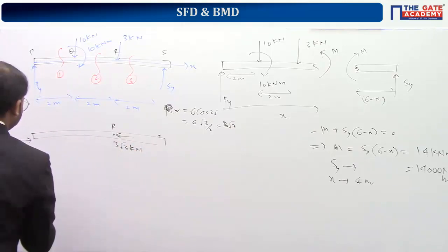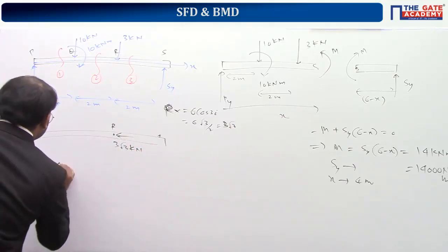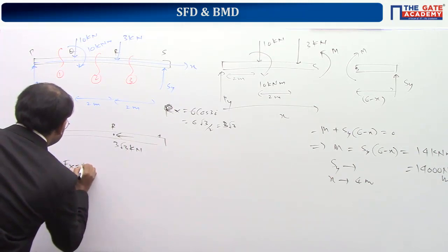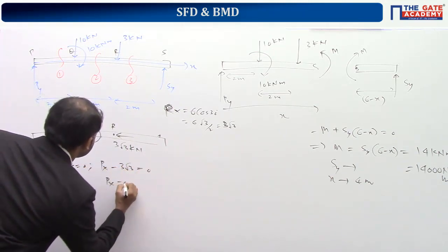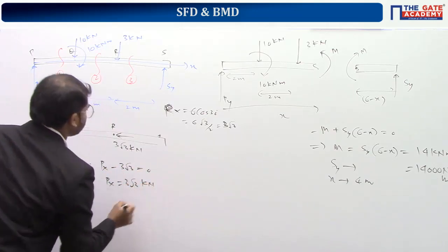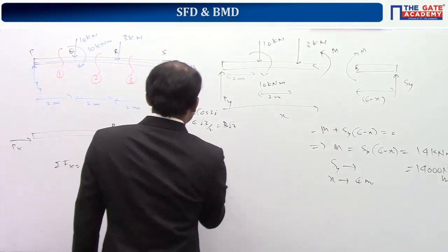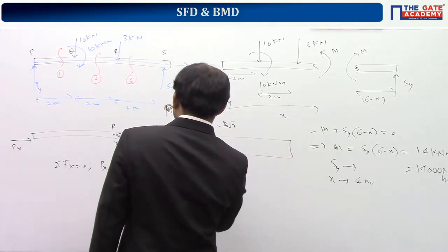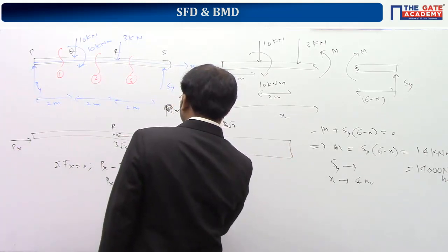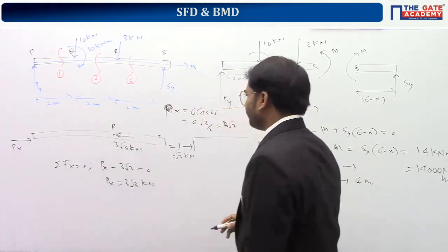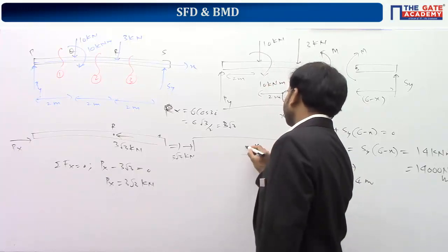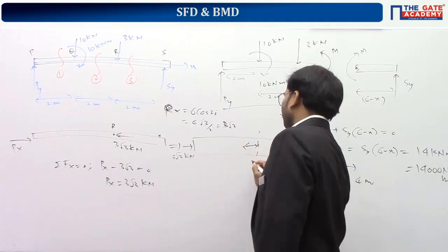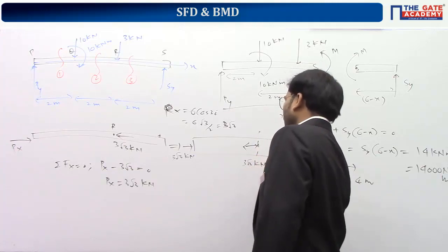If you apply the equilibrium condition, or you can apply net force and acceleration 0, you will get Px minus 3 root 3 is equal to 0. So Px will come out to be again 3 root 3 kilonewton. This implies the member is experiencing a force of 3 root 3 kilonewton at this location, and at the location R, it is again experiencing 3 root 3 kilonewton.